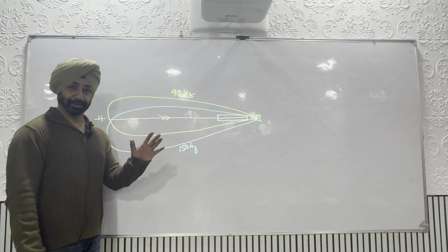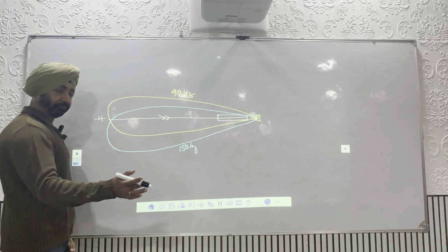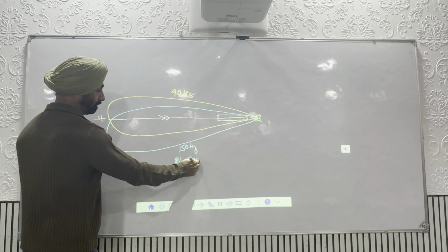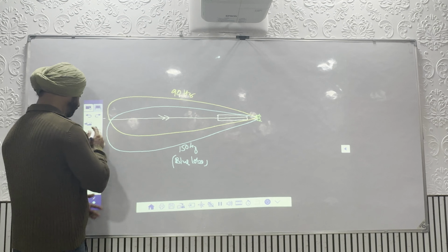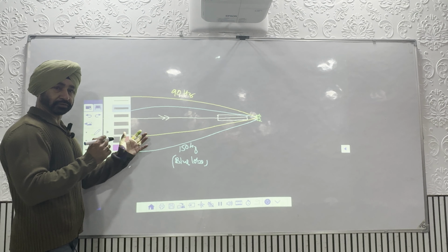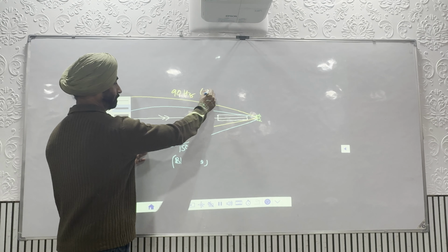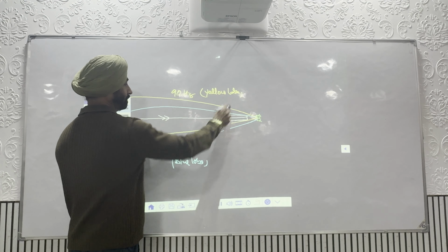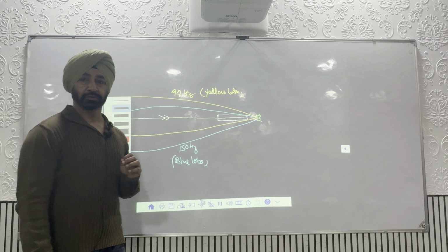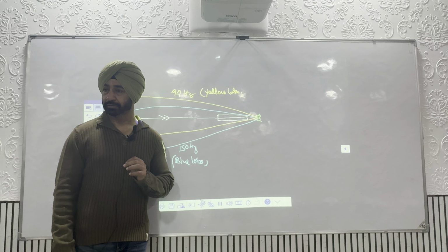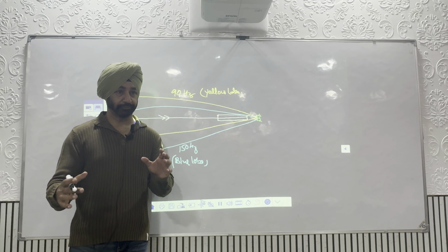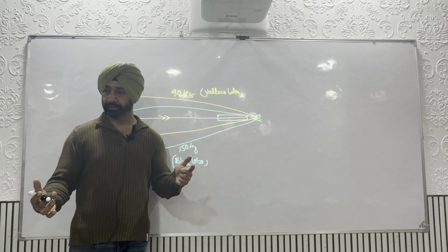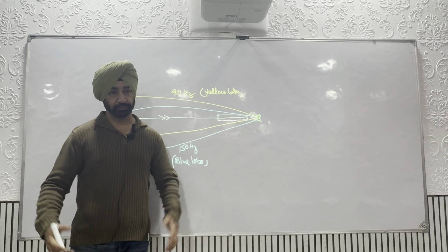Okay, it is not the color or something. The 150 hertz lobe, they referred to as the blue lobe, and left of the approach, the 90 hertz, they named it as the yellow lobe. So there are two different pieces of information on the carrier frequency. One is 90 hertz, one is 150 hertz. Now it has become very simple.